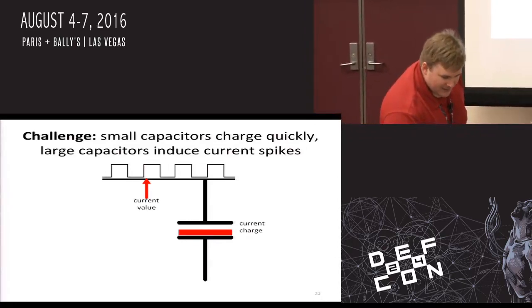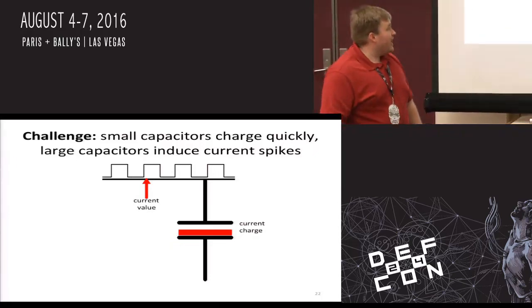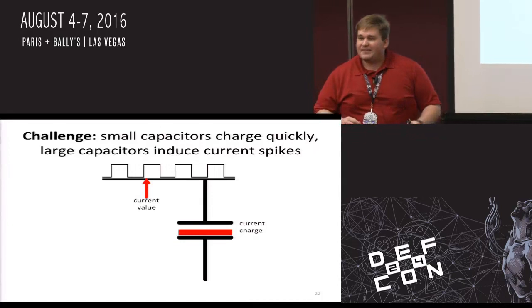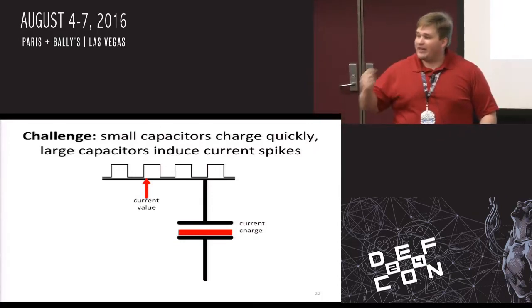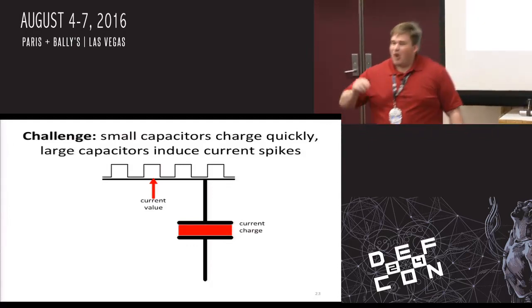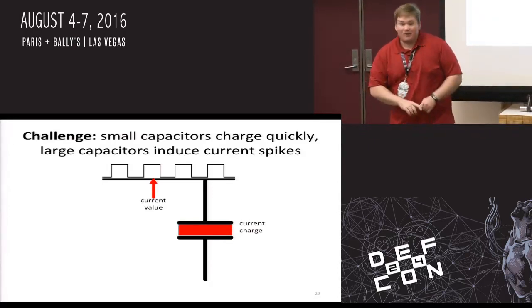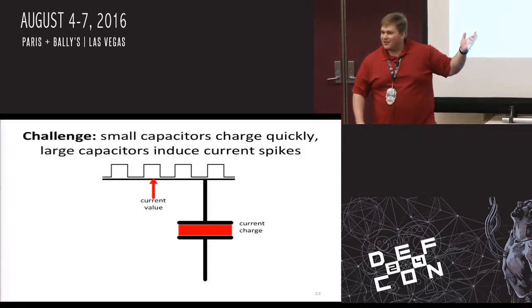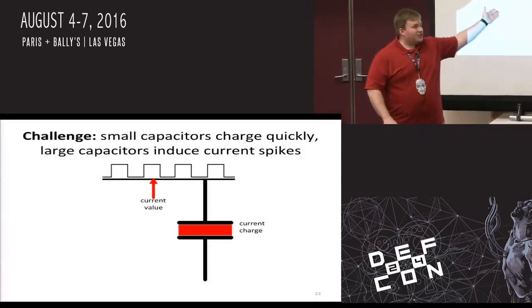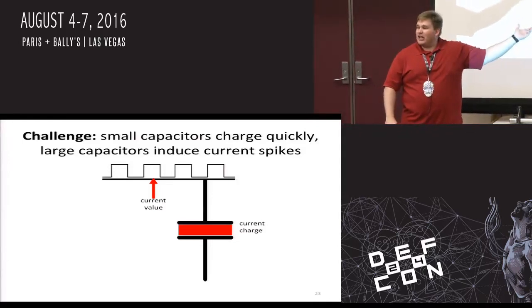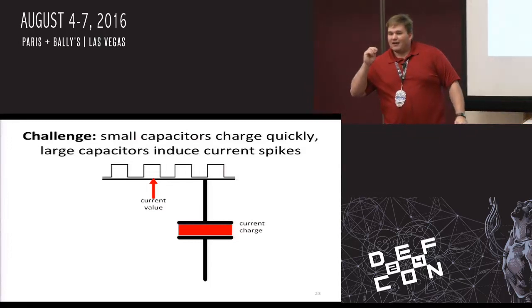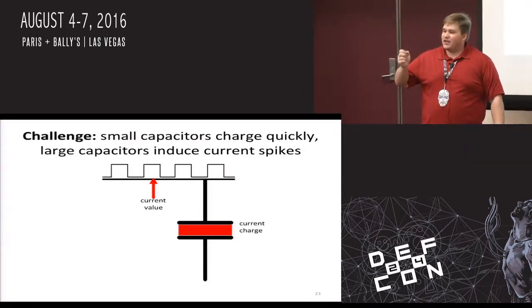The problem comes when we change values. Our victim wire goes to high, or to 1 value. And that basically starts accumulating charge very quickly on our capacitor. So quickly, in fact, that almost instantaneously, within a clock cycle, your capacitor is at full charge. But our problem was we wanted this complex state machine, not an attack which was triggerable within a single clock cycle, within a single toggle of a wire. So we just can't add a simple small capacitor to the design.